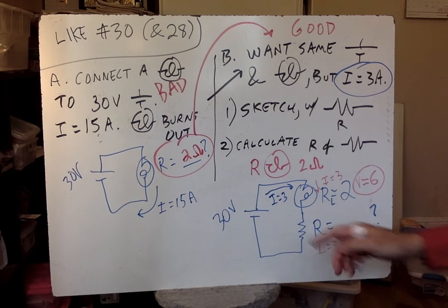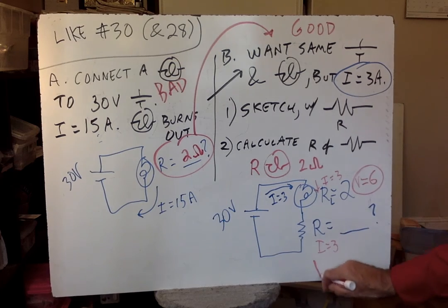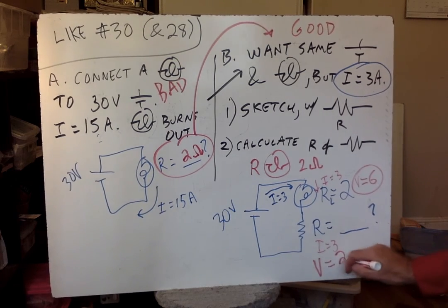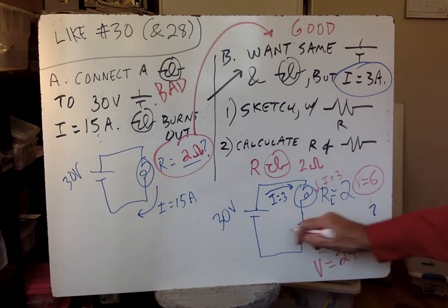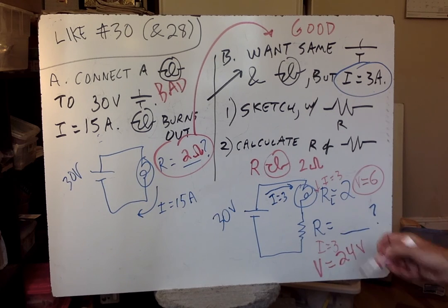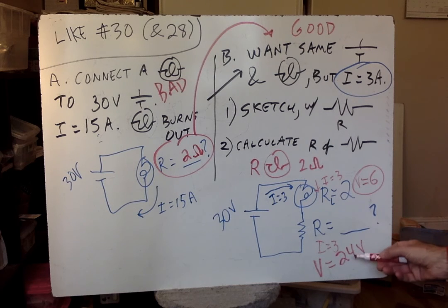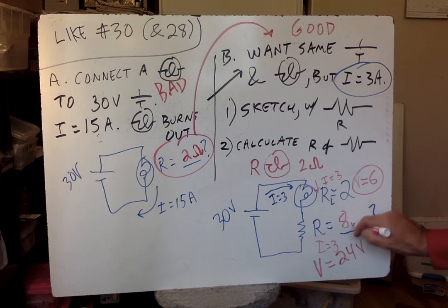All right, so how can we use that? Try the next step on your own. 30 volts here, 6 volts there. That means this voltage must be 24 volts. By the loop law, gain 30, lose 6, so you must lose 24 across the last part. Now we see 2 out of 3 items on this resistor, so we're going to jump on it, right? 24 volts, 3 amps. That means this resistance must be 8 ohms.